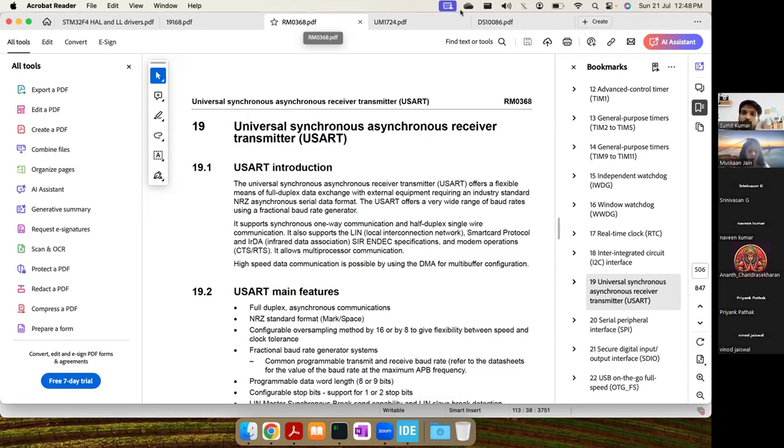Okay. So in asynchronous, we are using a separate acknowledgement signal, right? We are synchronizing it by sending the start and the stop bits. And in case of synchronous, we are just using a shared clock, which itself tells, so the acknowledgement signal is sent indirectly only. We do not need an explicit acknowledgement signal for sending the next data packet, right?